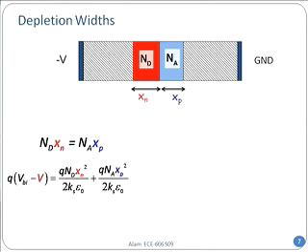And this is the second rule, that for the potential, the area under the triangle will have the same issues as before. Only thing in the equilibrium case, only thing that I have changed is the built-in potential. Now, in the presence of bias, it is not QVBI, but rather QVBI minus V, because my barrier has gone down by a certain amount. Now, do you realize why current would flow in that case?